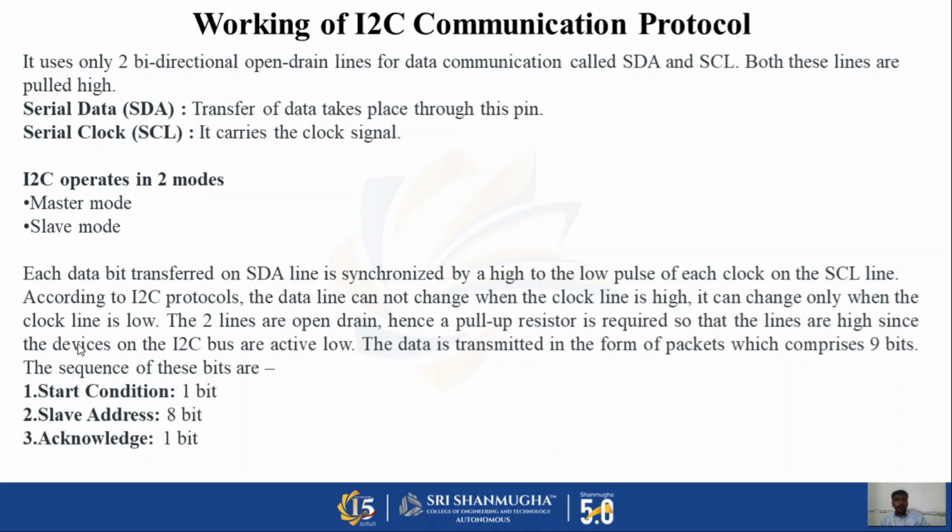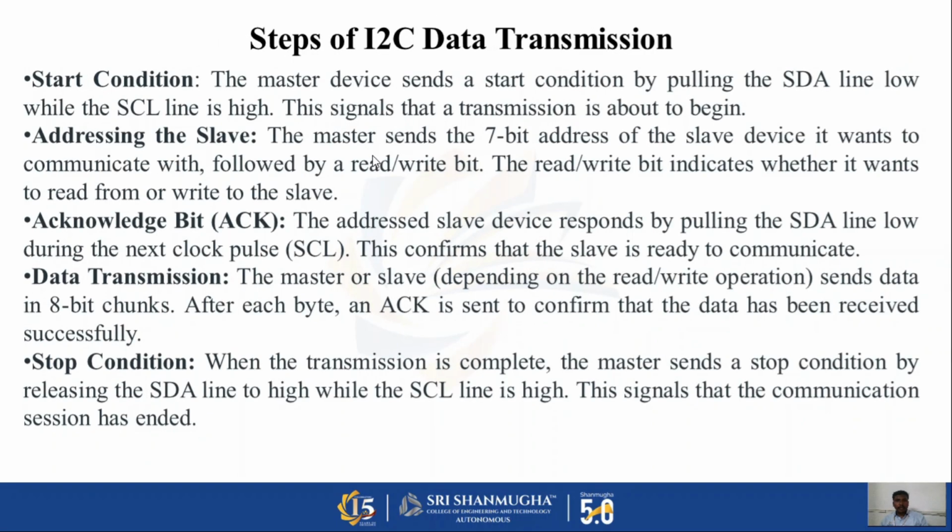Communication takes place in packets. Each packet contains a start condition, slave address, read/write bit, acknowledgement bit, data bytes, and a stop condition. This organized structure ensures reliable communication between devices. Let us understand the complete sequence of data transmission.